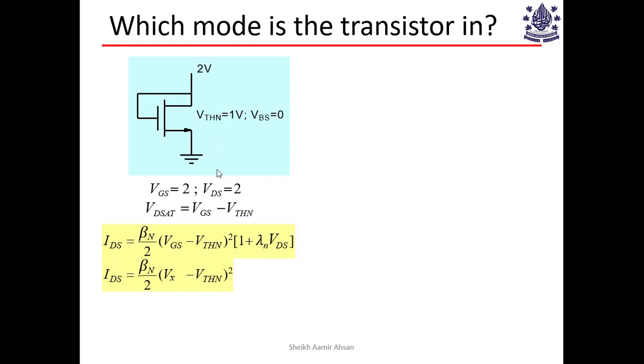So it's a 2-terminal device in which the current is given by the square of the voltage applied across these two. So if let's say Vx is applied here, right? So this Vx is VGS. Okay, so the current IDS will be given by Vx minus Vth whole square times beta by 2. Let's ignore the channel length modulation part for now.